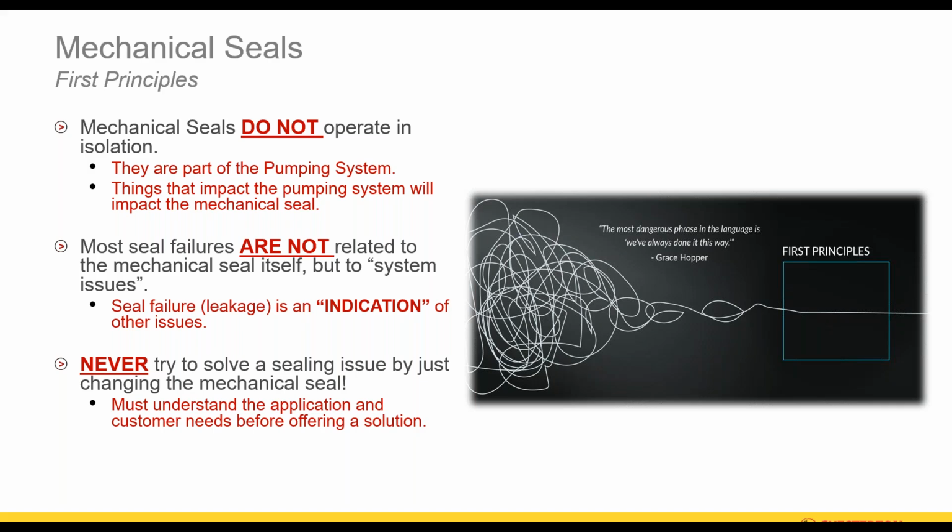The reality is, the more you understand mechanical seals and how they function and why they function, you'll start to understand the clarity of this statement. If a mechanical seal is failing, there's reasons why, and just putting a new mechanical seal in its place is not a prescription for success, because probably the things that have caused failure before will continue to cause failure moving forward, unless you address it in your whole applications approach with the specific application you're dealing with. So hopefully that makes sense to everybody.